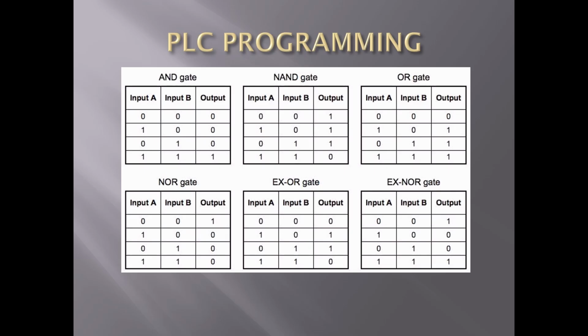You can go through and look at all the different logical outputs based on the gates and get a feel for how that works. If you look at the inputs as real-world devices, a switch, a sensor, any type of other real-world device that you can think of, i.e. wired to an input on the PLC, then you can start to think how you would logically control a PLC's program and affect real-world outputs.